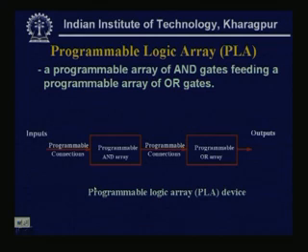So, the PAL structure and the compactness or flexibility of PAL to realize sequential circuits, as well as reuse some of the functions already realized to get new functions, that facility we have seen in PAL logic.